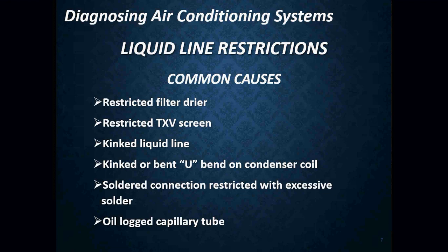Most of the refrigerant will be in the condenser, which will not necessarily cause high head pressure because of the reduced heat load of the evaporator, which is a common misconception. A lot of people think, well, if I have a restricted liquid line or a starved evaporator, my condenser pressures may be astronomically high because I'm not getting the flow through. Well, that's not always the case, guys. You have to look at your entire operation of the system.